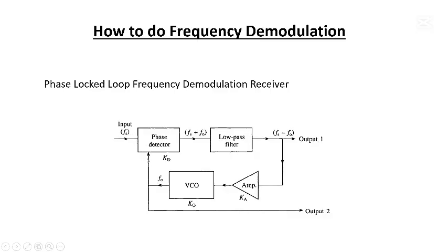That difference of frequency will generate a voltage, and the difference will be our output, which is used in the detection of the amplitude. If the difference of these two frequencies is higher, the output voltage will be higher. If it is low, the output voltage will be low.